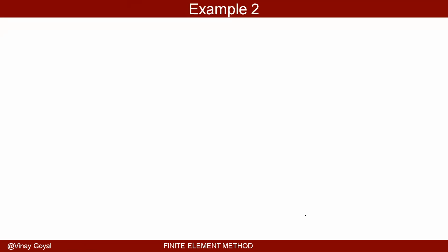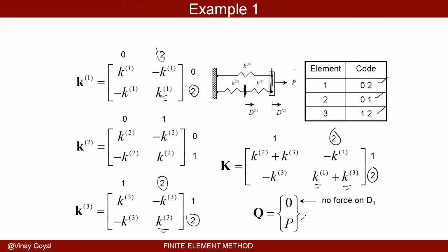So now all I have to do to solve for the deflections is to invert. So I have K times D equals Q. In a typical problem, K is fully known. The load is known. You apply 1,000 pounds, whatever. You can invert this K now to get D, right? The deflections.